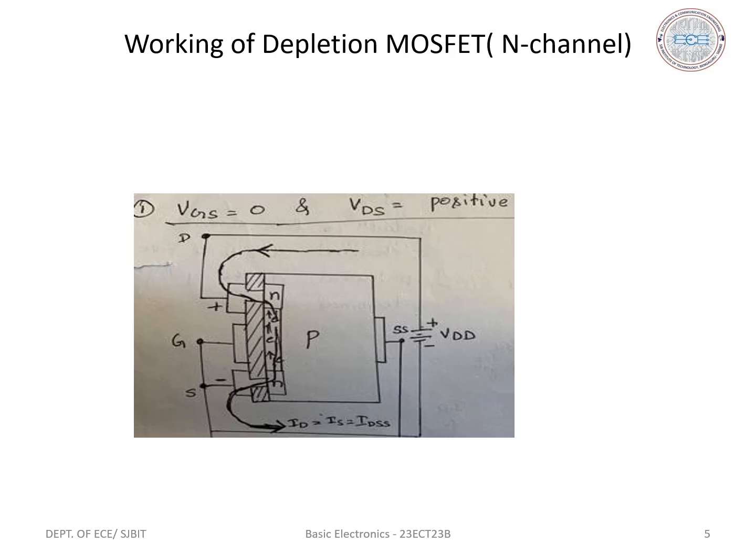Now positive voltage is applied between the drain and the source terminal. Due to positive voltage, electrons in this N channel will be attracted towards the positive terminal. In this way, current will be established in this N channel. If we keep on increasing VDS, the current will increase. At one particular point, at the point of VP, the peak voltage, the current will become saturated. Okay, so this is how it is going to work.